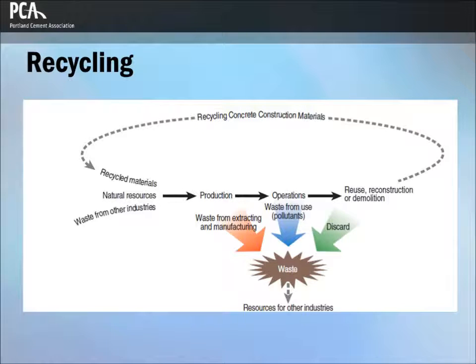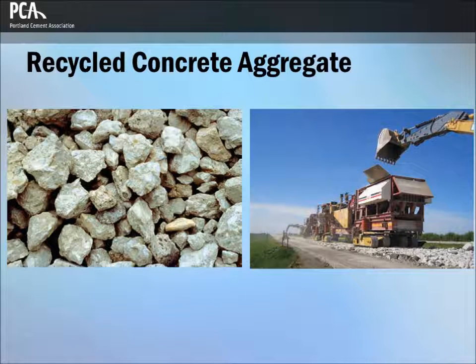Many concrete materials can be recycled after their initial use. Concrete from demolished structures can be recycled and is commonly reused as fill or road base. Paving trains can recycle existing concrete pavement. The crushed concrete can be used as aggregate in new concrete or as a base material.